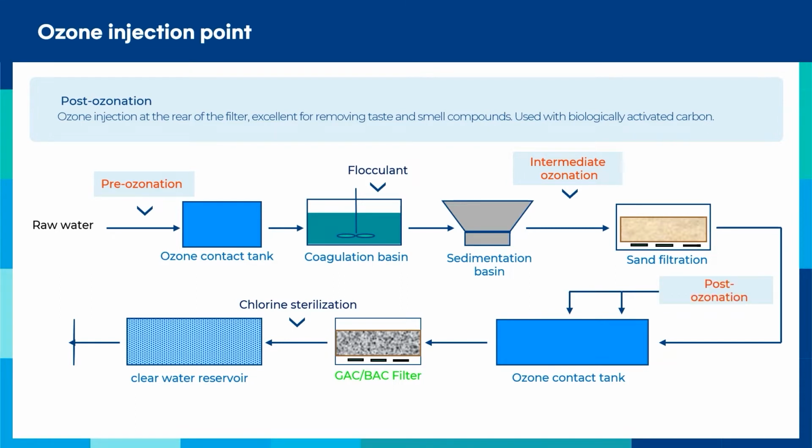In Korea, when raw water quality is very poor, pre-ozonation is additionally introduced and operated. Pre-ozonation can substitute pre-chlorination and achieve various water quality improvement effects, such as reduction of disinfection byproducts such as trihalomethanes, removal of algae, and removal of iron and manganese.